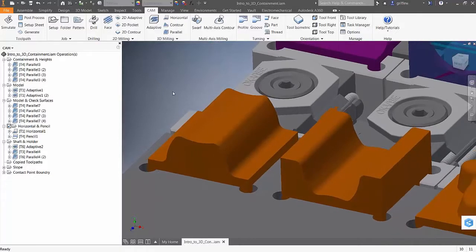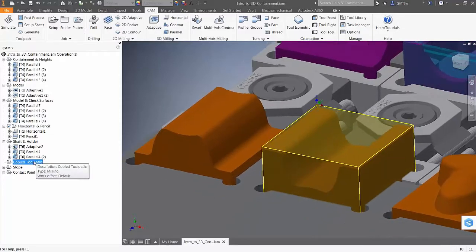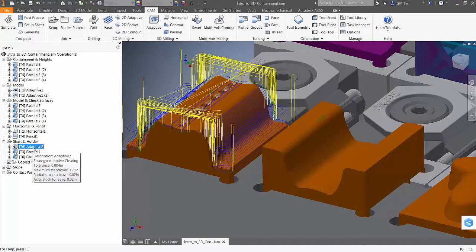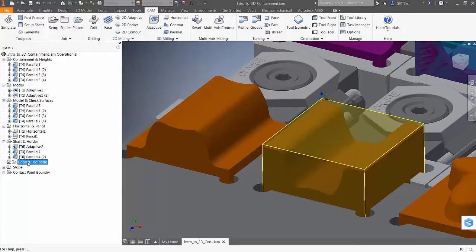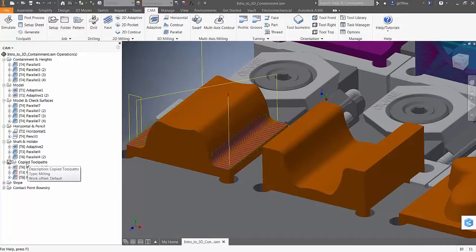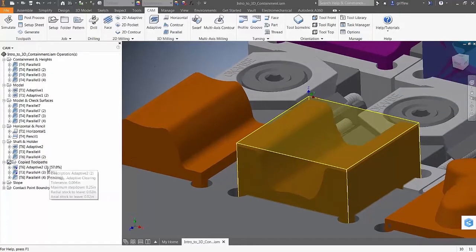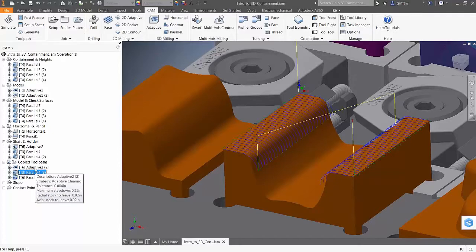Now earlier I talked about being able to copy and paste and having the toolpath automatically update on the model. We can also do this with a template. So when I look at the copied toolpath, again I'm going to hit Shift D to make that the default setup that I'm working with. So I'm going to select these, hold Shift, select those toolpaths, Control C, and while I'm in my copied toolpaths, Control V, copy those toolpaths over to the new setup. All I have to do is generate, and it automatically finds those places where we're containing those toolpaths. I'll let it calculate a little bit.